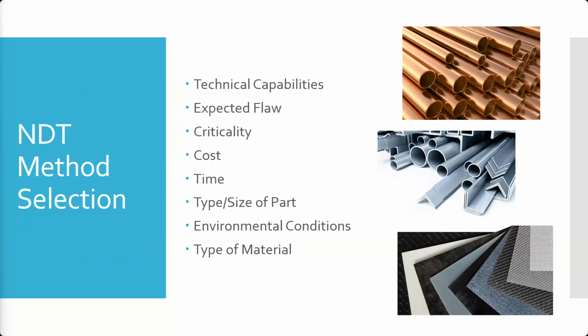Or, let's see, what's the biggest the flaw can be when you find it before it becomes a problem? That makes sense? So if you can find a flaw when it's visible and it's still considered serviceable up to the point where you can see it, why would you bother doing these more expensive, more involved, more technically complex processes if you can just wait until it's visibly worn, or you can measure it with just a pair of calipers or something, right?